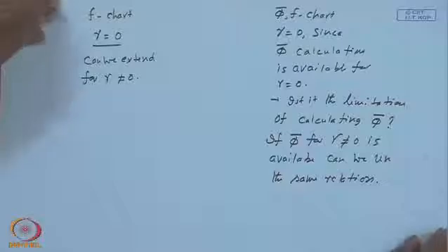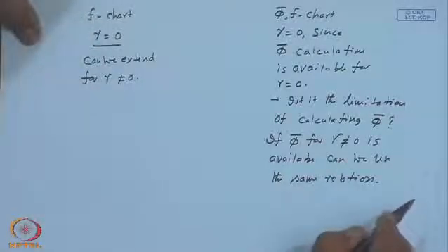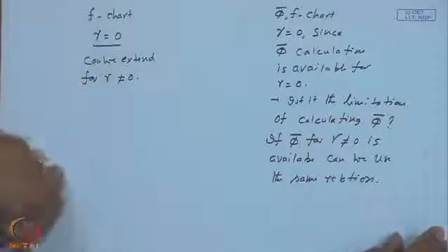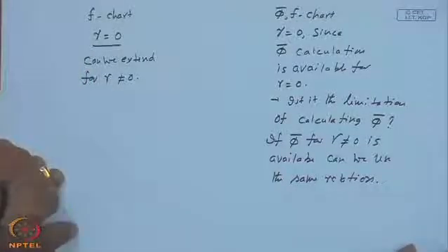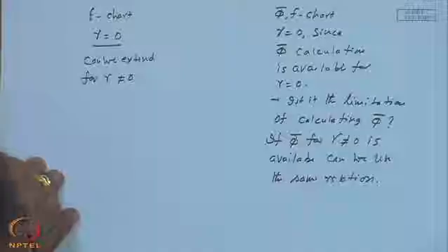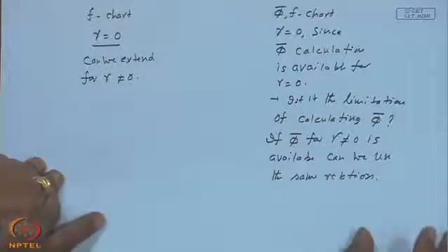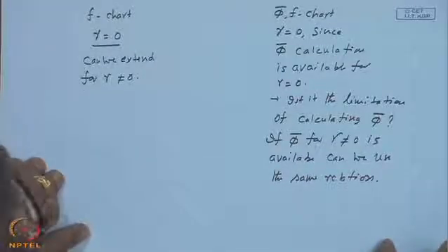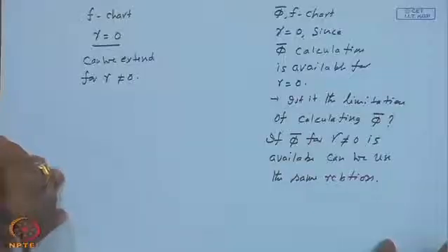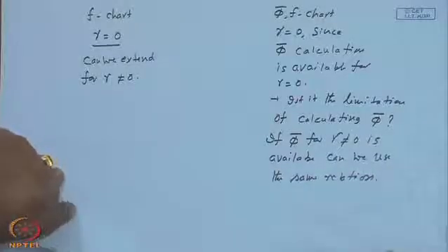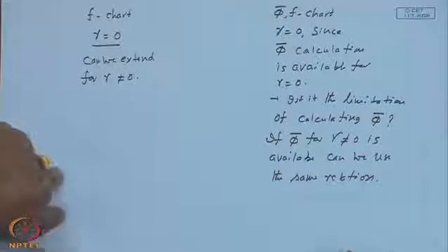Somebody may take up this problem, though if I remember right, Collares-Pereira and Rabl suggested that for concentrating collector or gamma not equal to 0, replace this phibar and use the same correlation. However, some verification needs to be done based upon the simulation results.